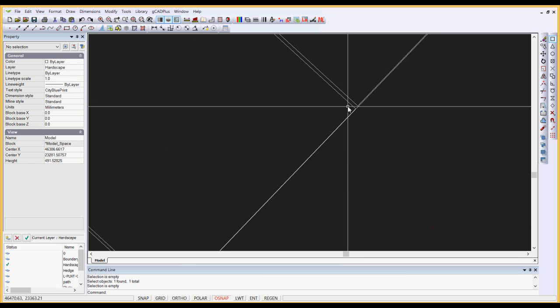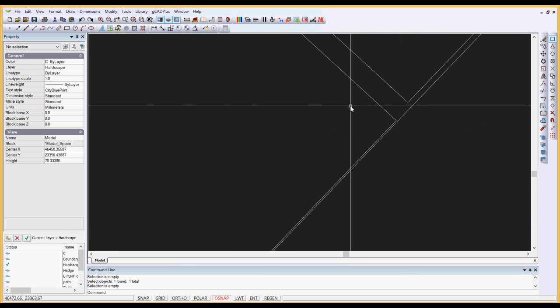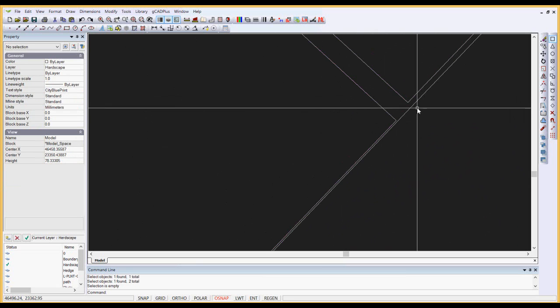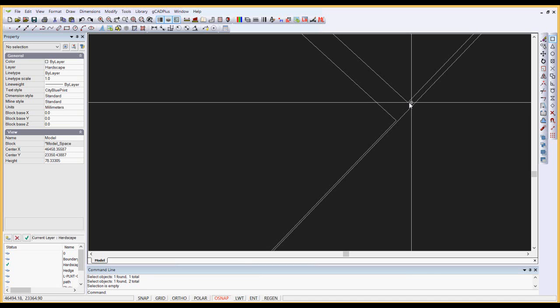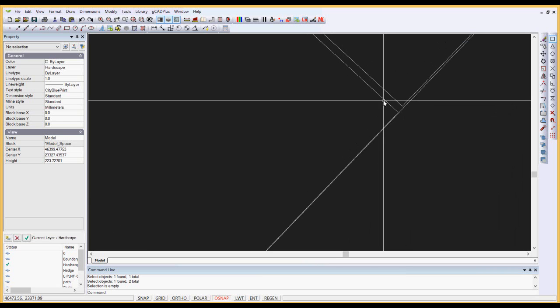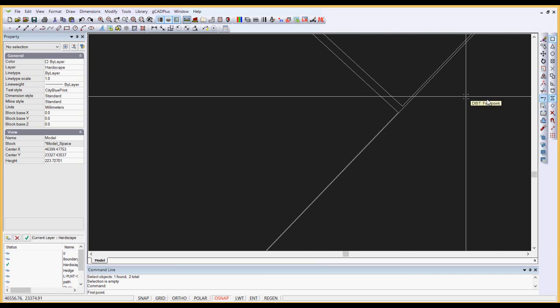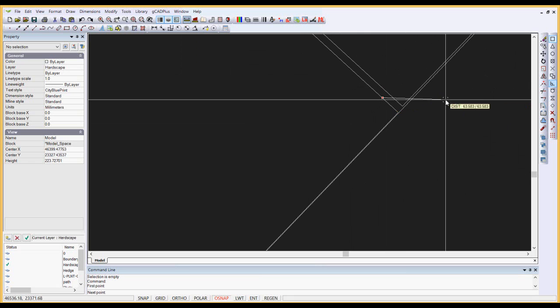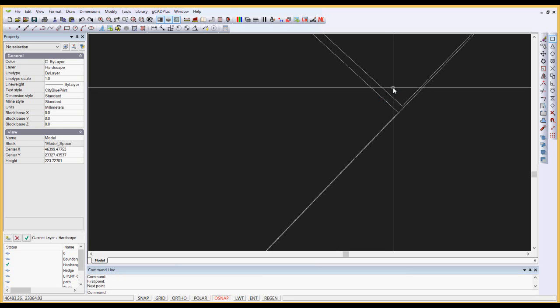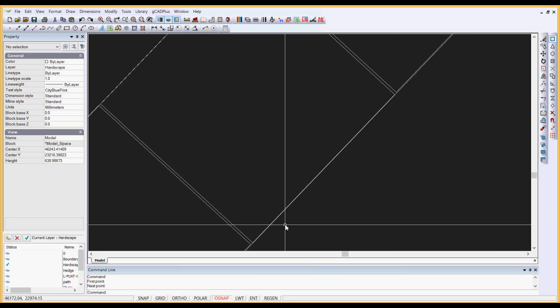Next thing I'll do is jump in here and just have a little look. You can see here, if that represents one paving brick and this one another, you see that the gap between the line, which is meant to indicate the edge of the path, and the bricks themselves varies quite a lot. Let's check the gap between the pavers by using the distance command, and we'll snap near here and go perpendicular to that point. The gap is 9.097, so 9mm gap. Maybe that's meant to be a 10mm gap.